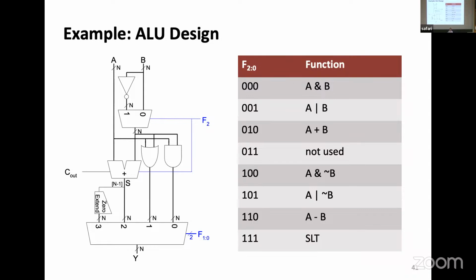Yes? Is there a reason why the 0, 1, 1 is not used? Good question. No, not used. The way they have constructed it, it doesn't create something useful. And they wanted 7 functions, not 8. So one of them was not bound to be used. They tried to figure things out. So for example, the addition and the subtraction are actually the same, 0, 1, 0, and this bit just flips the inversion. So somebody did some sort of optimization there. It wasted one function.